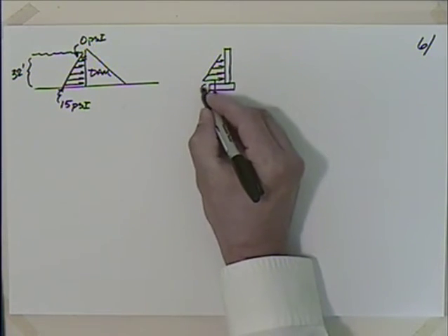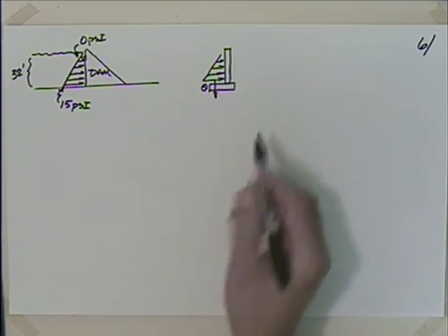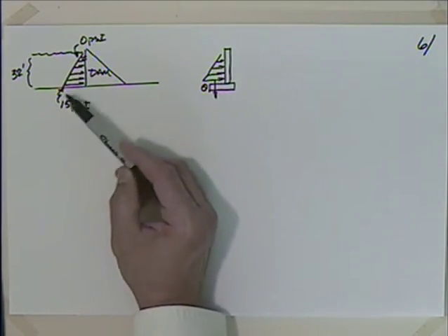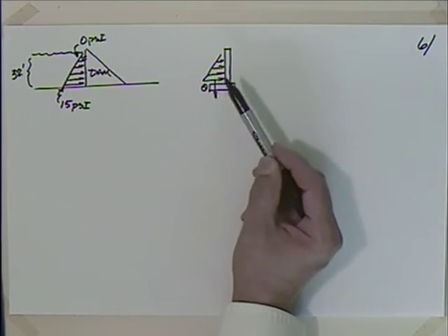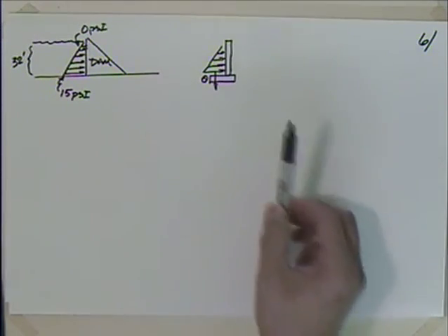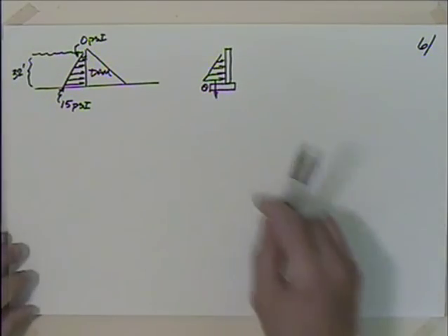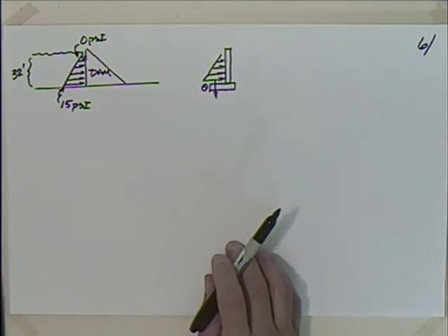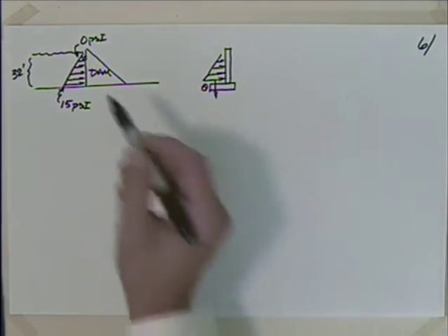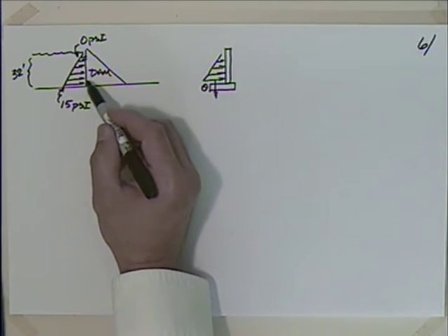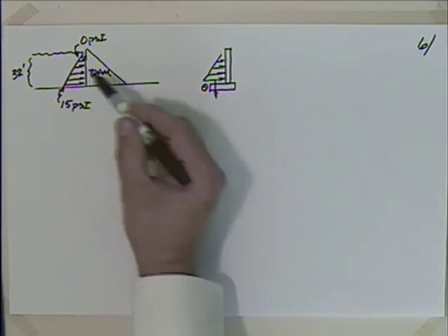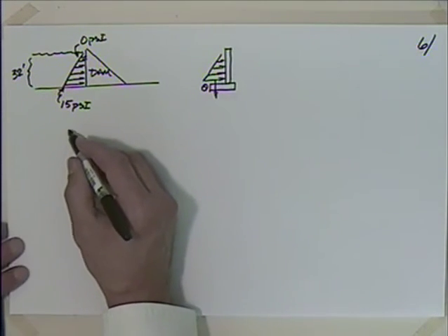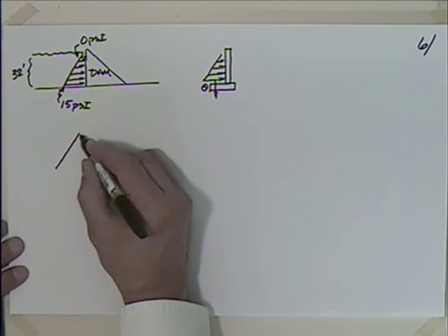And a lot of times this is some fraction of water. You put some drain in here, you put a pipe in there to try and keep this drained out so it's dry, and then you'll have some fraction of water. You don't want this to liquefy in there. And there's lots of things that when you go to soils, you're going to talk about active pressure or passive pressure, whether you're allowing this to rotate slightly and whatnot. So a lot of good stuff there. So even if you don't get into the business of building dams, you use these concepts a lot when you deal with soil pressure. So let's continue on with our work here.